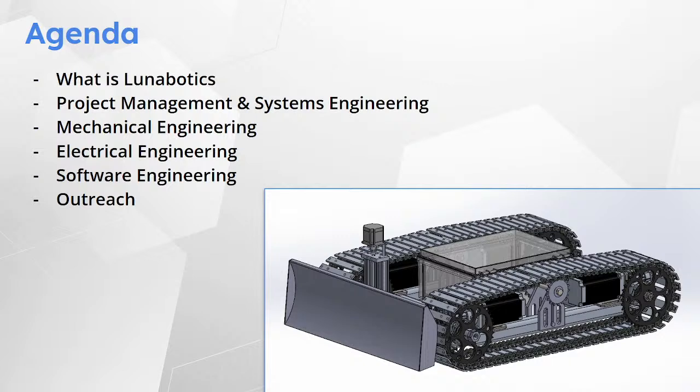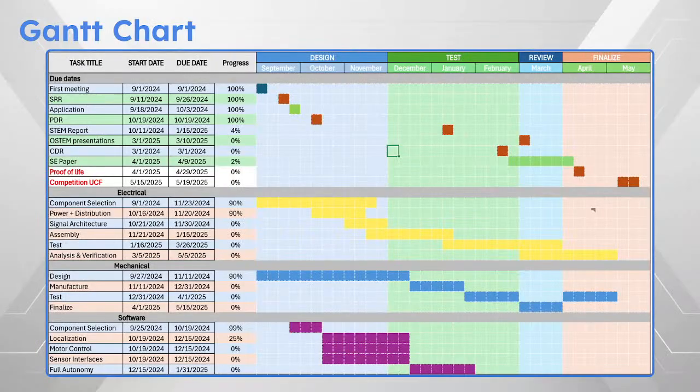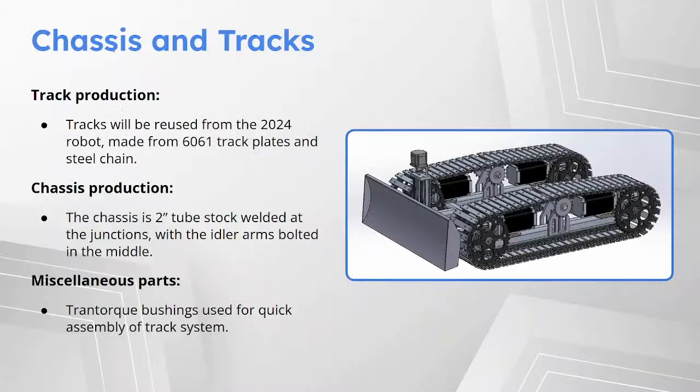As far as the power sensors, they can really be located anywhere on the power supply wires to the motors themselves. Really, it's just a splice in and then out. They're good up to, I believe, maybe 25 amps, so they can handle a fair bit of current.